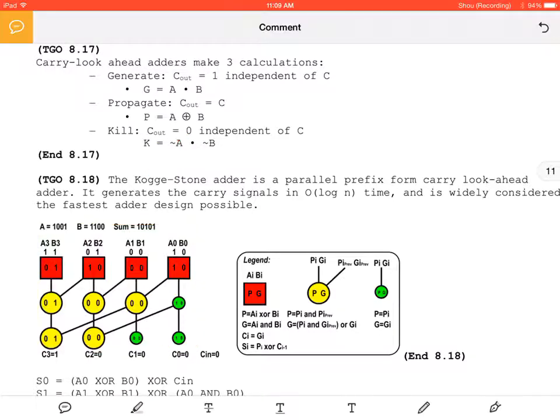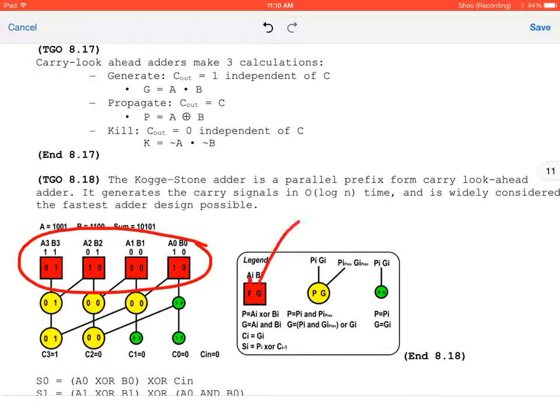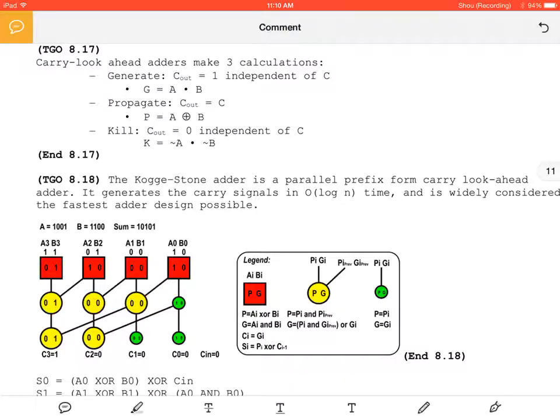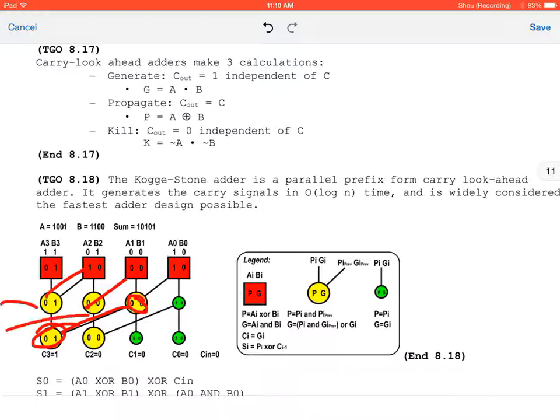But the general idea is here we have our 4 main adders, right? So the way it works is you're outputting propagate and generate, carry in, and SI here, so sum and carry out, right? And then as they're running in parallel, see how it cuts across there instead of doing 1, 2, 3, 4? It actually goes by factors of 2, right? So this one's going to go 1 and 1. So next 2 are going to go 2 over and 2 over and so forth.